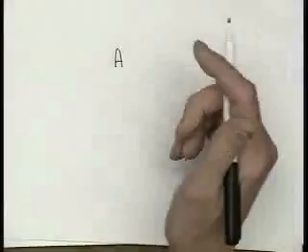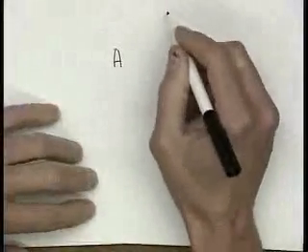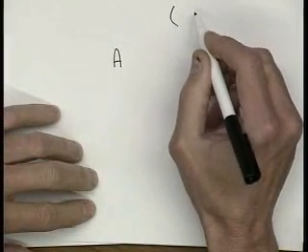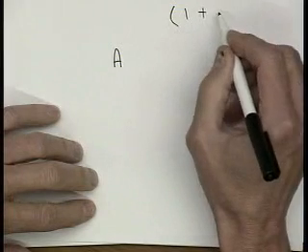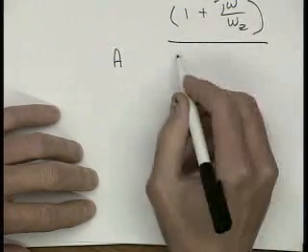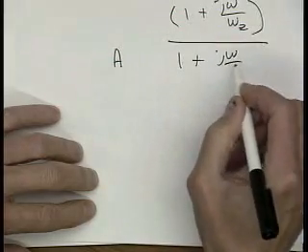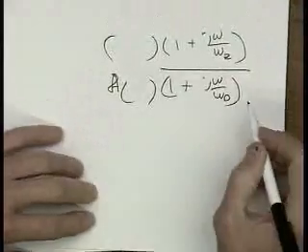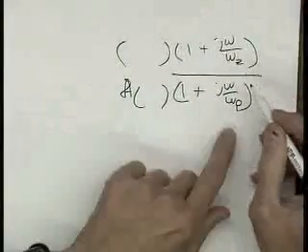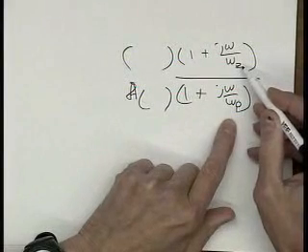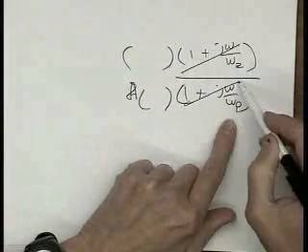When you look at the results of SPICE, they'll give you a bunch of poles and zeros where the pole and zero are almost exactly the same point. There'll be 1 plus j omega over omega z, and this is what a transfer function would look like, over 1 plus j omega over omega p, and plus all sorts of other ones. Notice if omega p equals omega z, then these two terms will cancel out.